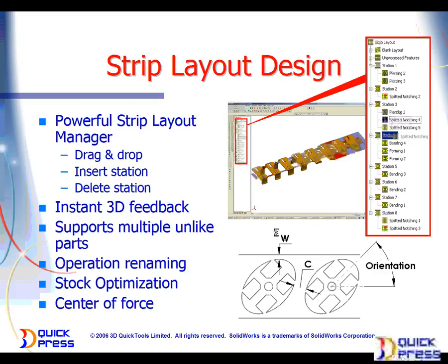Strip layout design will allow us to put as many blanks into the strip as it can have, of course, no stock, so you can do stage tooling and have multiple tools set up, so it is flexible. Also, you can rearrange the processes. We create all the piercings and the bending and all the different features in it, and then you rearrange how you want to notch it.